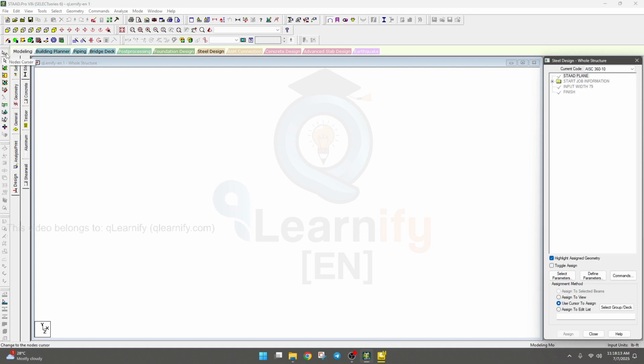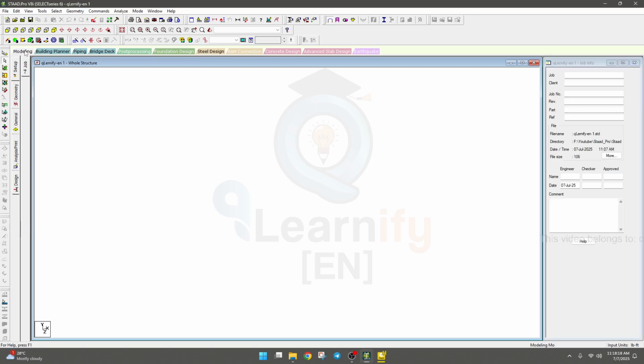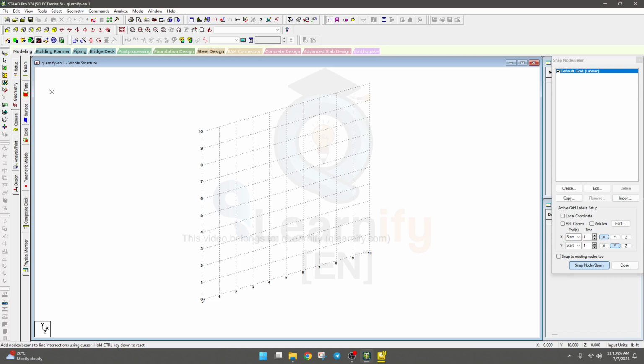Now here if you see, they have a node cursor. That means if you go modeling here, so if you want to see a geometry, so if you want to select node, then you will use this option. If you want to select beam, then we'll use this option. For plate, for surface, then for solid cursor, we'll use all of that option to select different things in later here.